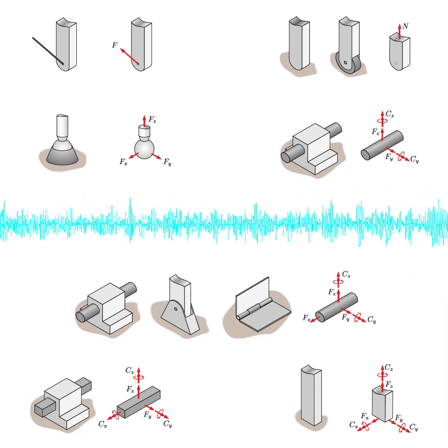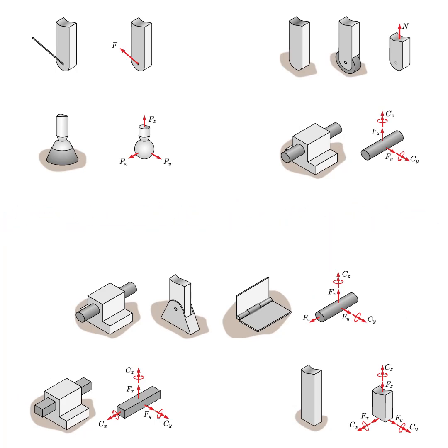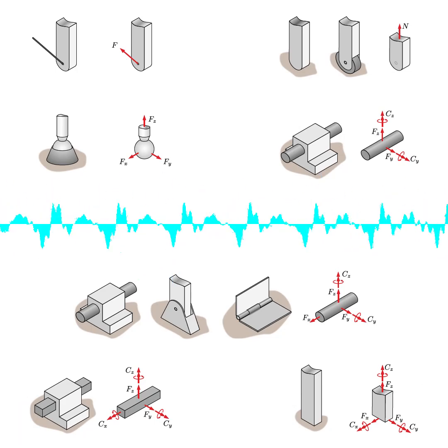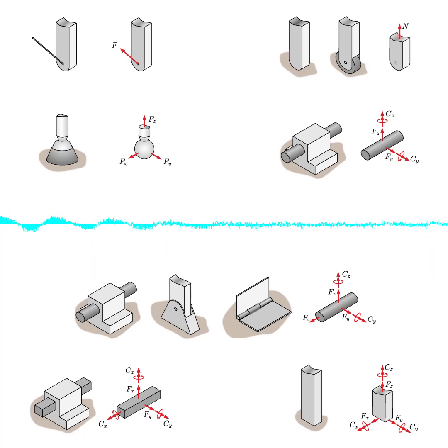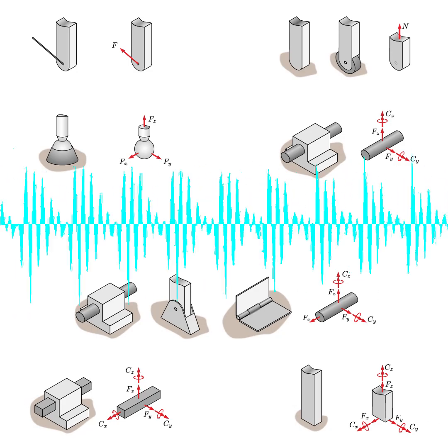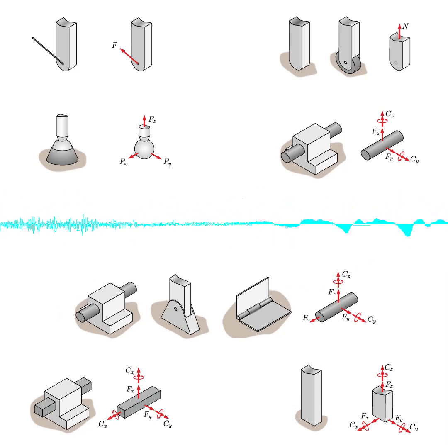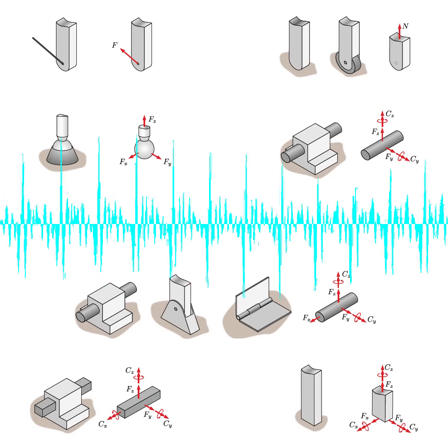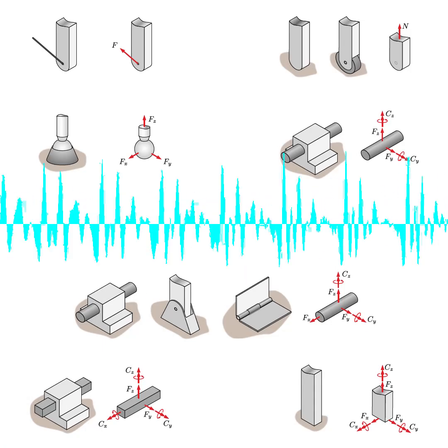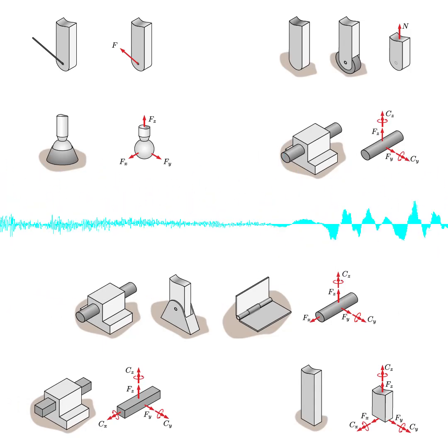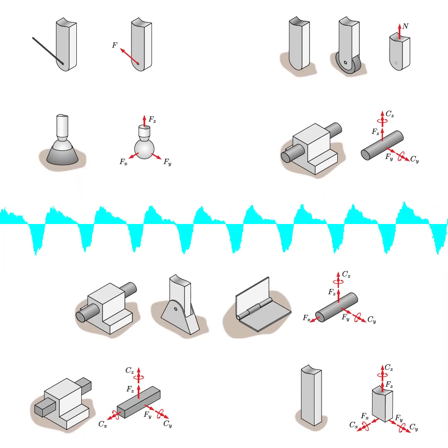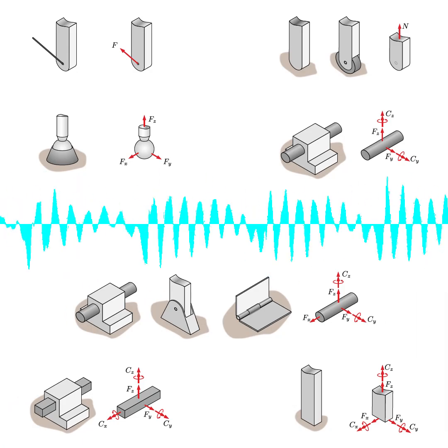Okay. What's the second check for 2D systems? So the second thing to check is the direction of your reaction force components. If all of those forces are parallel to each other, then the system is probably going to be unstable for translation in the direction that's perpendicular to those forces. So imagine a beam that's only supported by rollers that are providing vertical forces. That beam is free to move horizontally. Right. I could just slide right off those rollers.